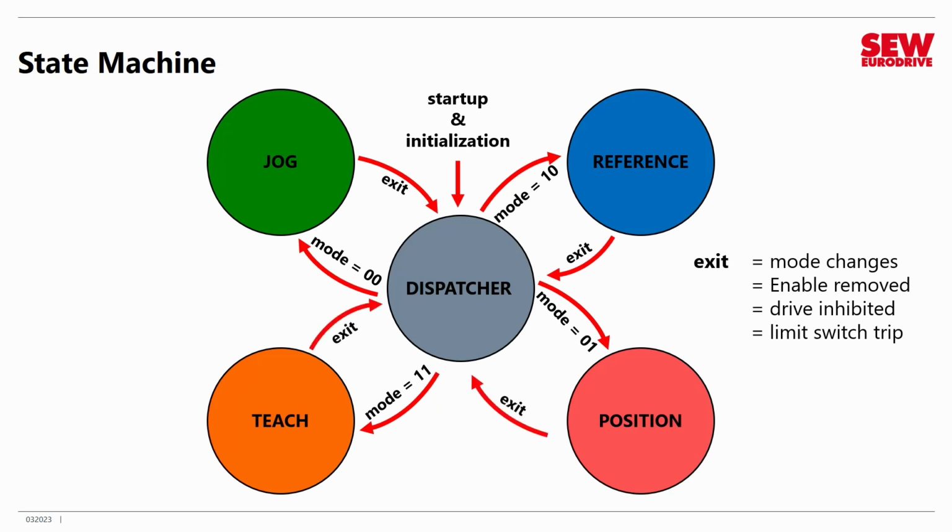Of course, you have to manipulate the outputs appropriately as you go along. For example, you may have to stop the motor or start it. You may have to turn lights on. There are a number of things that you may have to do in there, but that has nothing to do with exiting and entering the states. The states are basically a description of how the program behaves. So study this diagram carefully because this is kind of your roadmap for what you're developing.